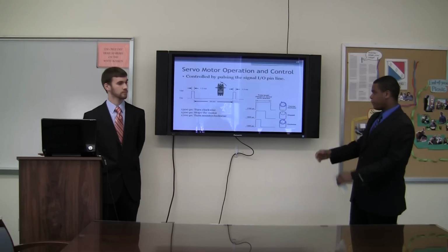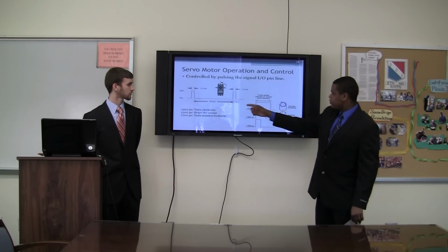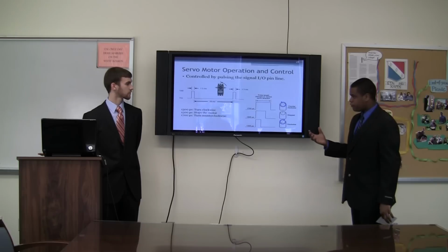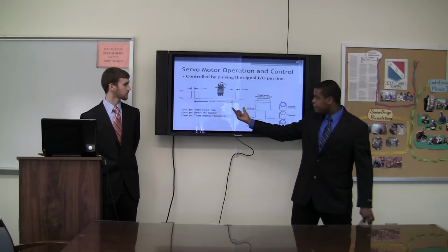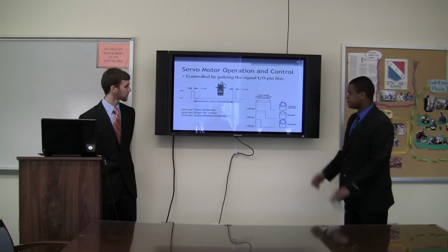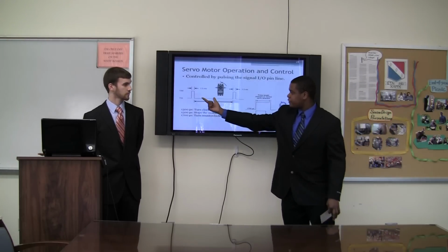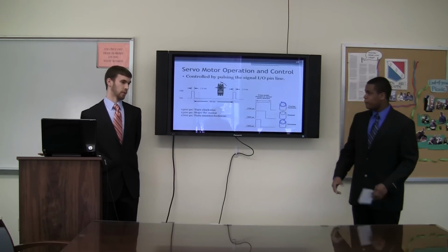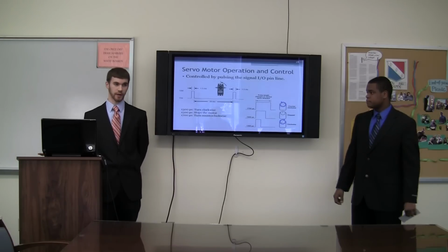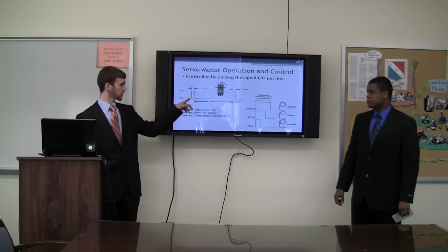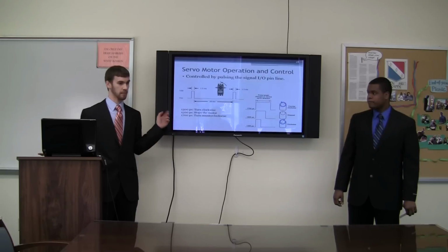And to control this servo motor, we basically provide a pulse width modulation signal. From the rising edge to the falling edge, you have a 1.5 millisecond pulse that you use to stop the motor. And it has to be separated by a 20 millisecond pulse train. So the period would be 20 milliseconds plus the 1.5 milliseconds, so a 21.5 millisecond period. Right. To turn the motor in either direction, you would decrease this pulse width to a minimum of 1.3 milliseconds.